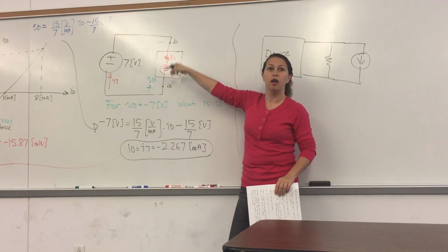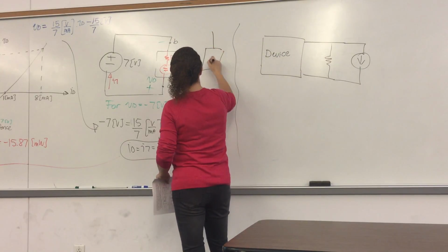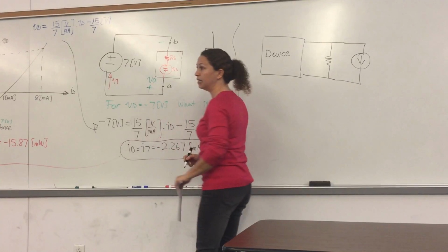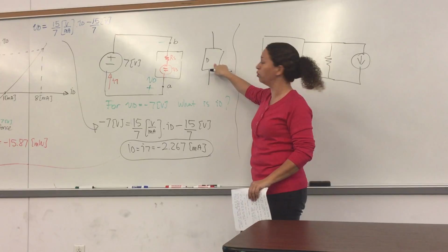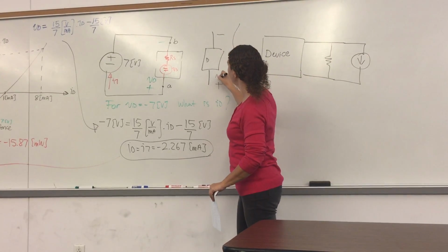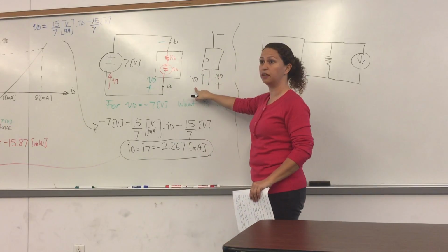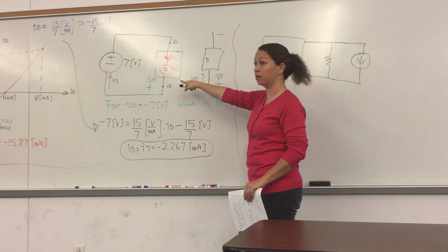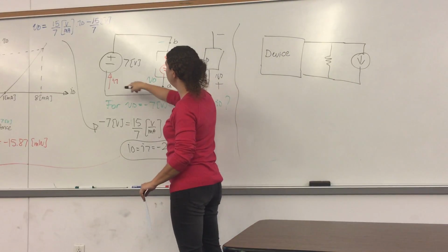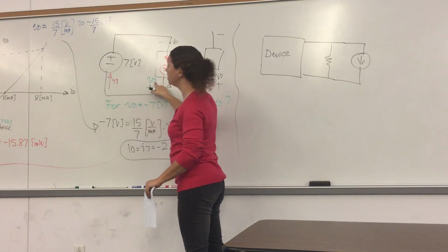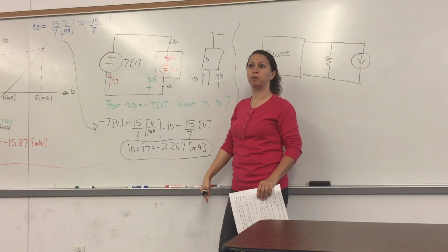If you go back to the beginning of this class, when we gave you a device like that, let's say device D, and if I ask what is the power absorbed by this device D, what would you do? You would have your voltage, VD, your current, and passive sign convention, it's VD times ID, right? Doesn't matter what's inside here. Same here. So if you're calculating power absorbed by this guy, it's going to be VD, well actually minus I7 times VD. VD being the voltage across both components, not one of them. Make sense?